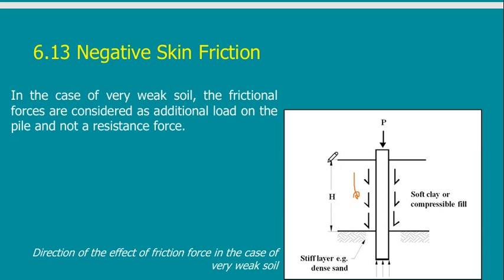So if you calculate here a load capacity for this layer that can carry the pile, it will be acting as a load on the pile. This is very important. What is also more important, if you have a small layer here at the bottom, this is only the clay, and all of this is sand. But because the sand is standing on the clay, the sand with time will also move down. So all of this will be a negative skin friction, or a negative friction on the pile.